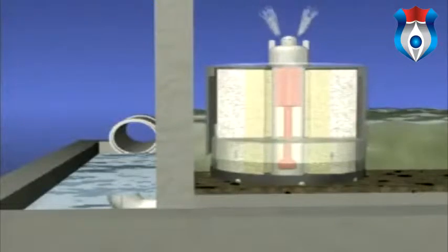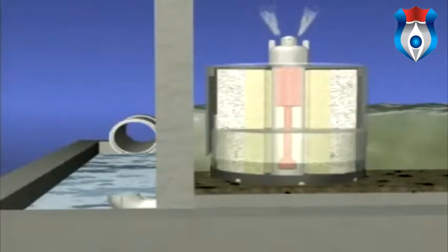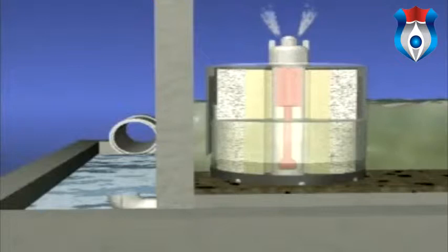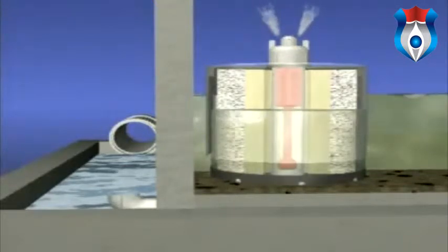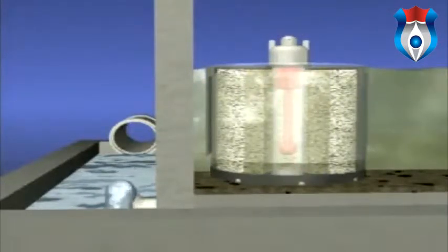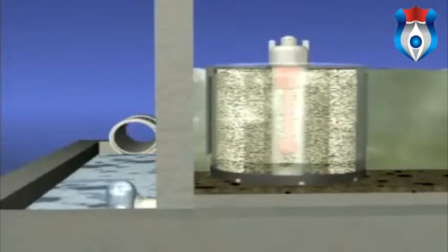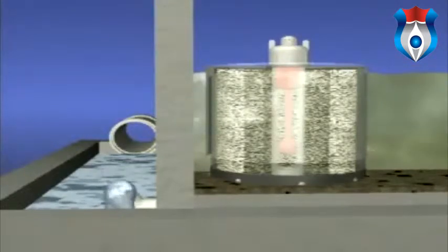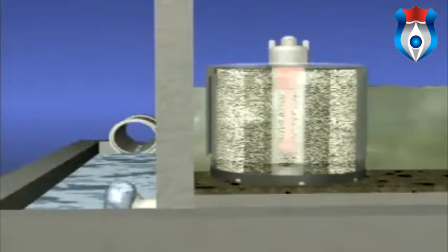The siphon mechanism is activated as the vault fills with water, and the trapped air is purged from under the filter cartridge hood through the air relief valve. When the water in the cartridge reaches the top of the float, buoyant forces pull the float free and allow the filtered water to drain out into the underdrain manifold for discharge. At this point, the air relief valve closes to create the siphon effect.